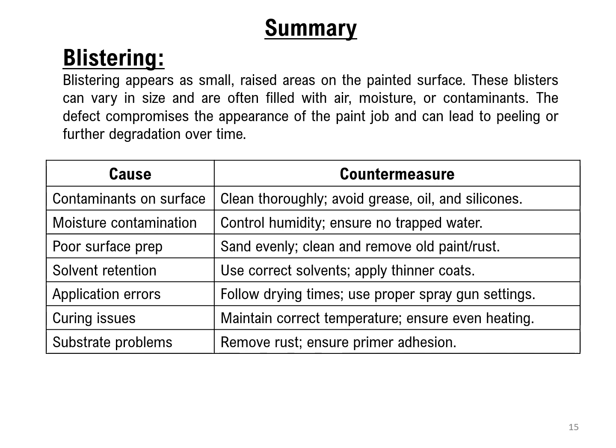Number 5. Application errors. Follow drying times. Use proper spray gun settings. Number 6. Curing issues. Maintain correct temperature and ensure even heating. Number 7. Substrate problems. Remove rust. Ensure primer adhesion.